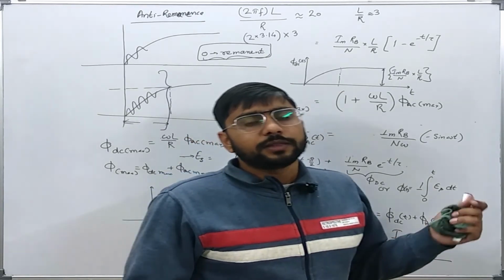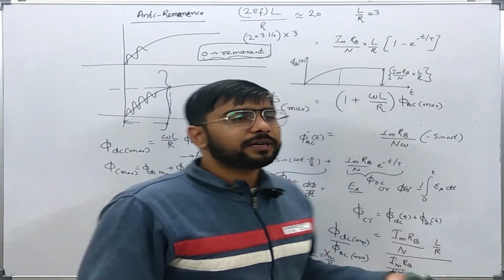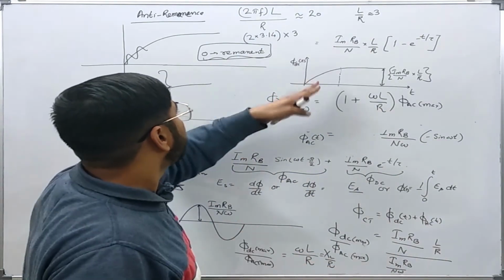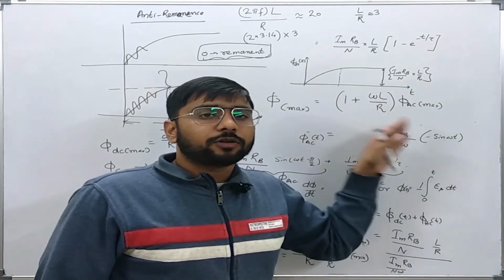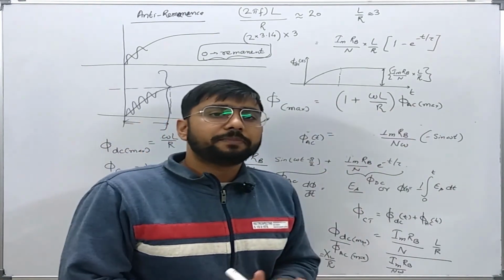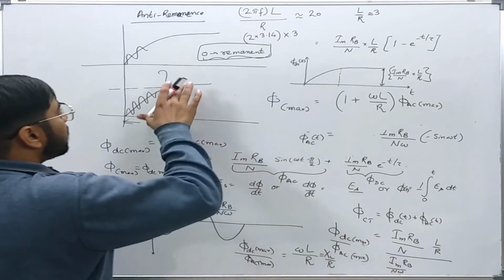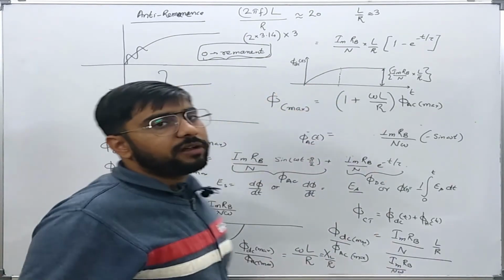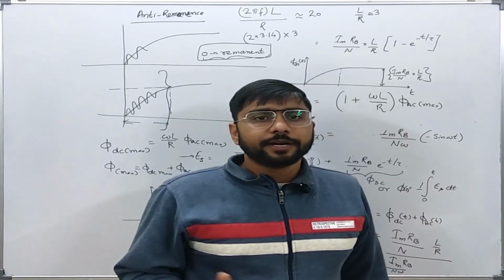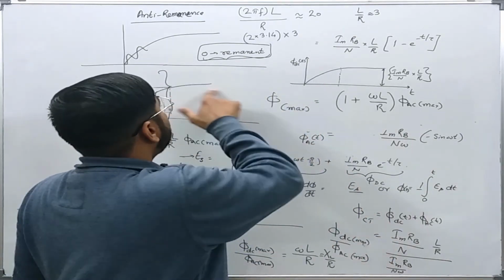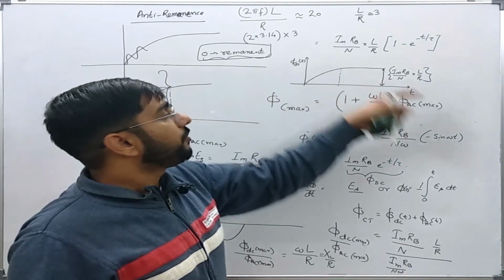Now the overcurrent relays usually do not depend much on the waveform of the current. They just depend upon the magnitude, and magnitude-wise the value of current will still be very high. So overcurrent relays are not that much affected by the DC transient, or the transient behavior of the CT.